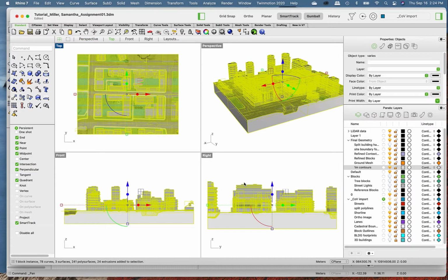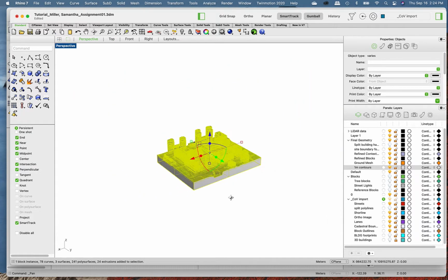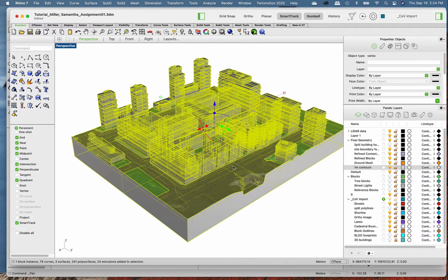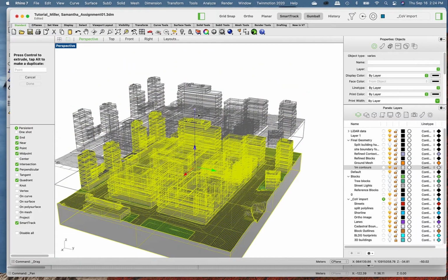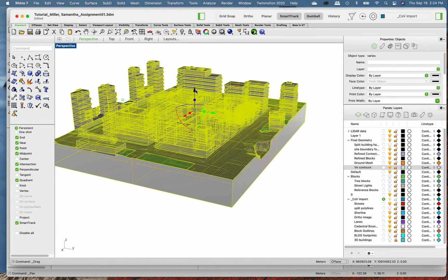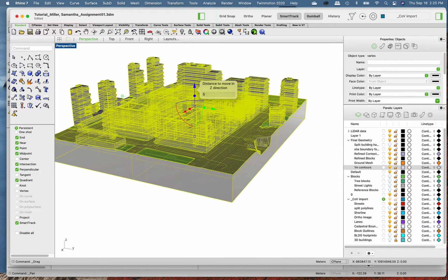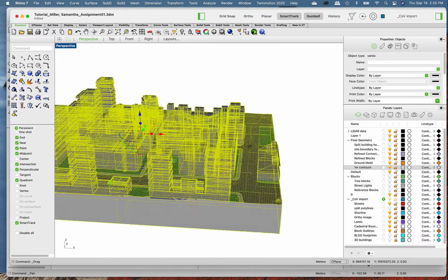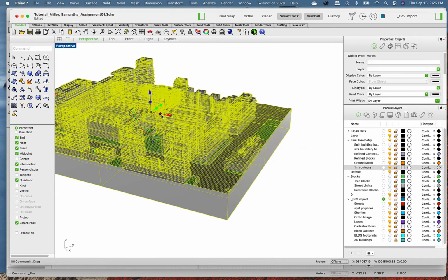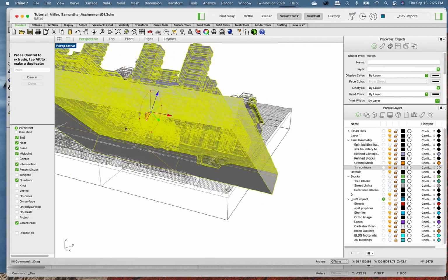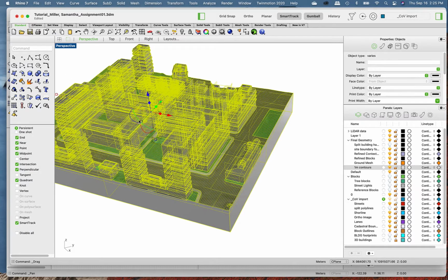So let's say I wanted to move this entire object. I'm going to go into the perspective view here. Let's say that I wanted to move this entire object in the Z direction. So I would pick this gumball. I can either move it up just like that, or I can click on the Z direction and it's asking me for a distance to move in the Z direction. And since I'm working in meters, I can type in 5, for example, and that's going to move it up exactly 5 meters. I can also rotate around these axes by just using these little curves. Not sure what they're called, but they just allow you to move in these different axes.